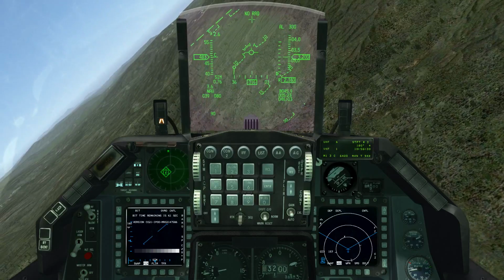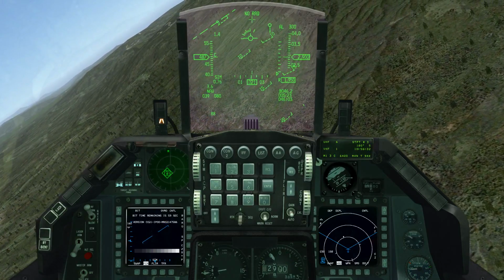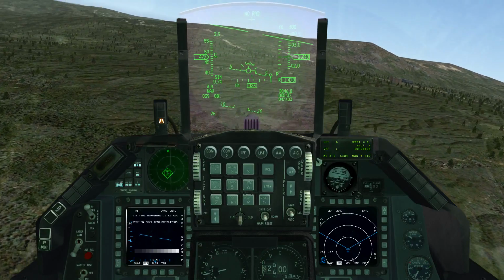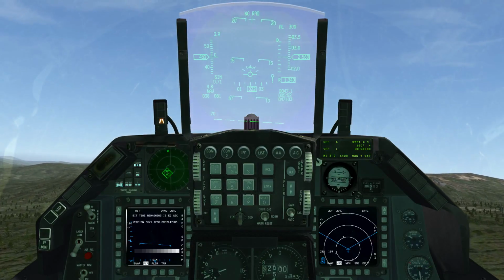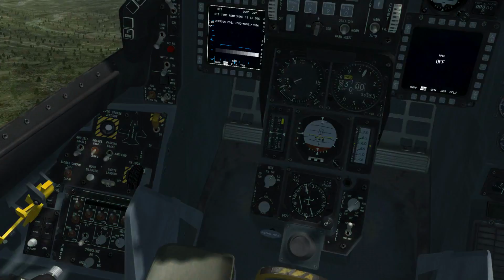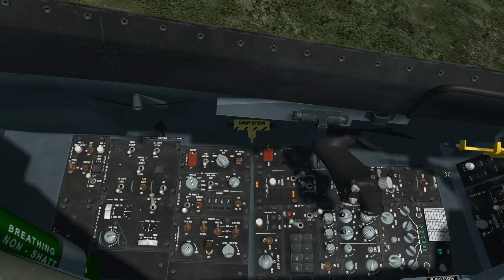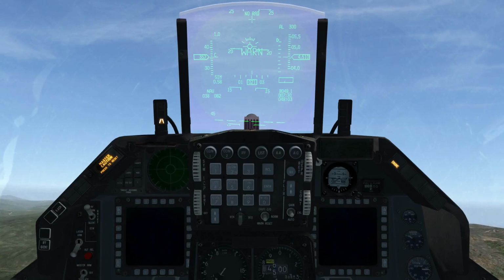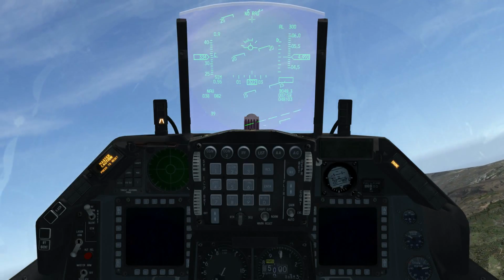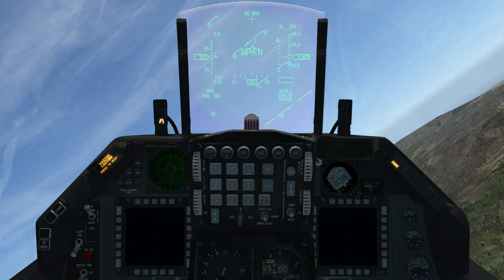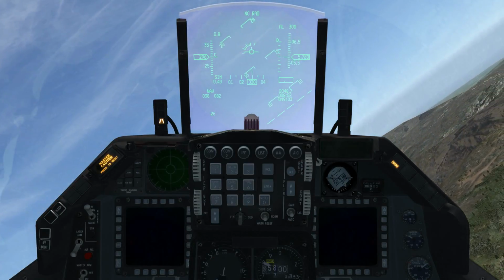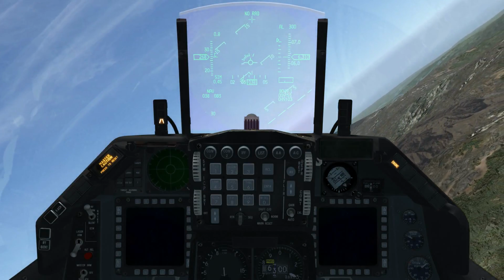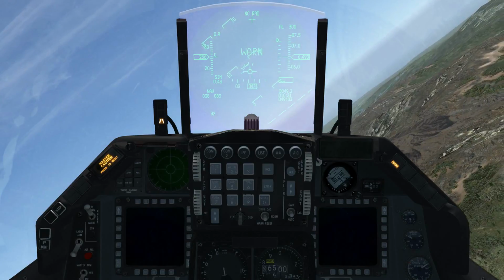So we're doing 400 knots, we're in the weeds. I'm going to shut off the fuel, and then I'm going to correct it. I'm going to roll wings level and zoom, trade some of this airspeed for altitude, and immediately come over and get the JFS switch to the on position. Alright. And then I'm going to advance the throttle, do a throttle idle detent, and then throttle to idle. And so that system worked.